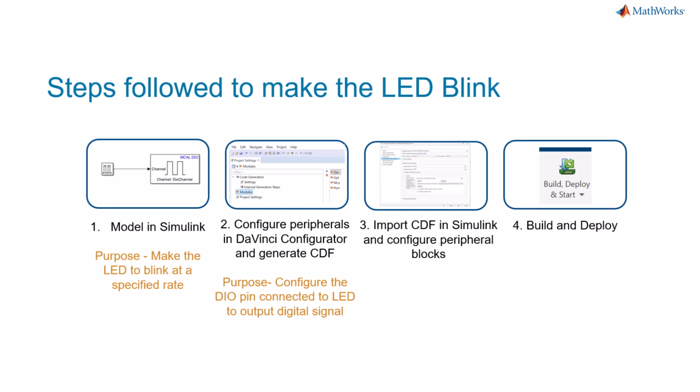Model the LED blinking behavior in Simulink, configure DIO peripherals using DaVinci Configurator or any third-party MCAL configurator tool, generate and import the CDF file into Simulink, build, deploy and run the model on RH850 U2A Starter Kit.